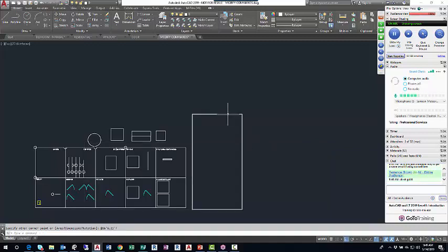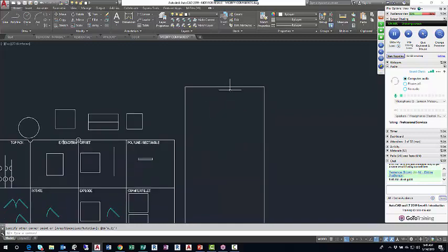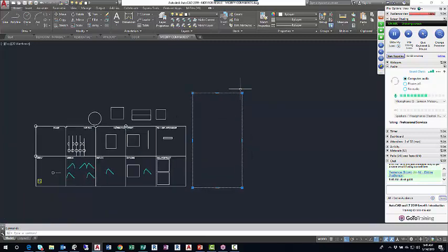And that's the result. One of the cool things about dynamic input, this is sort of a sidebar, is that if I click on that polyline and hover, not over the edge grips, but over the corner grips, I can get a temporary readout of the horizontal and vertical dimensions. They're hard to see probably on screen, but it's showing me 16 feet 6 in the horizontal, 31 feet 7 in the vertical.